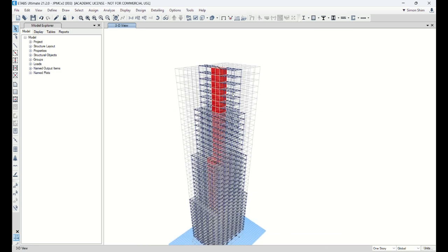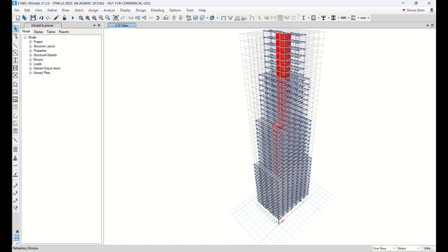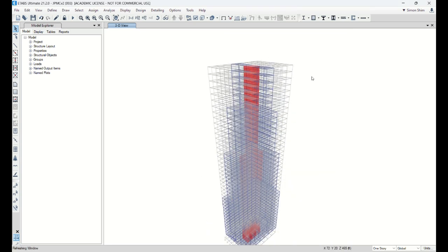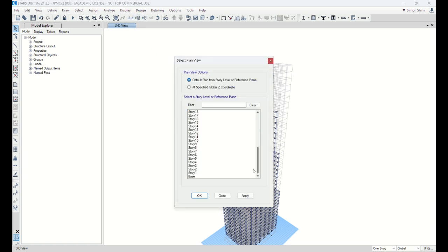Now, you maybe can redesign it if you can, because I see some W8 by 21 and W10 sections, which are relatively small sizes. We usually don't use these W8 or W10 for high-rise buildings. All right, now I'm going to move to the lateral system.